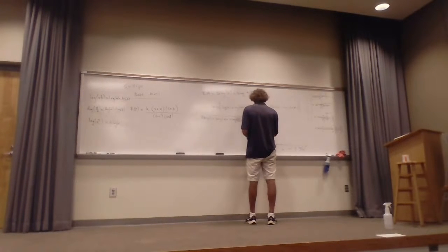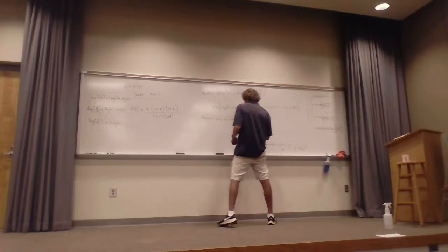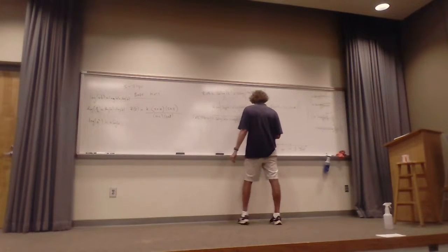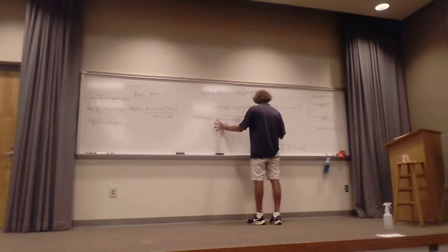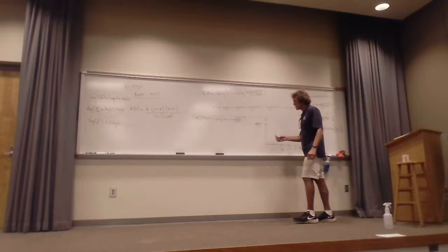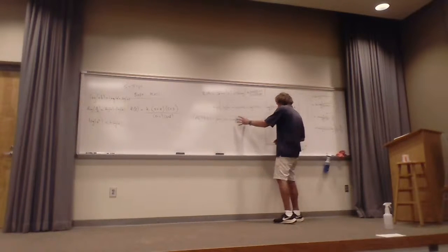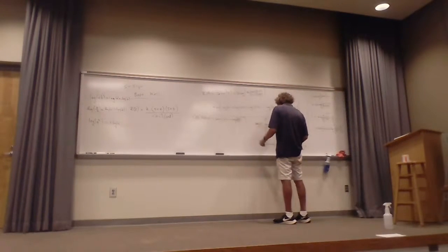Now on this axis, what I'm going to do is plot this function, and this is in dB already. I've got 20 times the log of that. So when I plot it, it starts out with this value at very low frequencies, and it has 20 times log of A here. Now, if you look at this at omega over A much, much less than 1, you all with me on this? So omega is much less than A. Really, we're talking about the log of 1 here, aren't we? What is the log of 1, people? 0, right? So there is no value to this until you hit the value omega equal A, wherever it is.